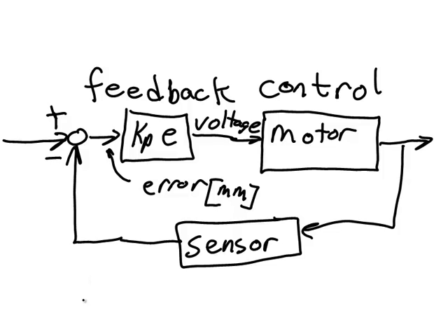In other words, Kp has units that are something like volts per millimeter, or this may be different depending upon what your position error is measured in. If you're doing a rotational position control setup, then this might be volts per degrees of error. In order to find a reasonably small value for Kp, you have to think about what are the maximum and minimum limits that your system might have on these two units.